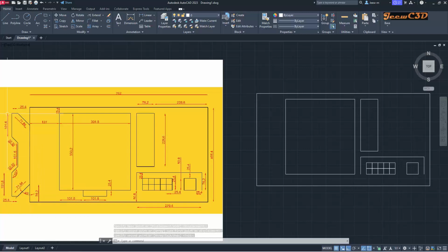Now I am going to create this part. I am going to create this part using a polyline. So I will launch my polyline command. So I am going to go to this end point. I am not clicking there. Now I am going upwards using the object snap tracking. Make sure your object snap trackings are turned on. So I want to have 76.2 length upward. Now it's okay. Now I am starting it from here.